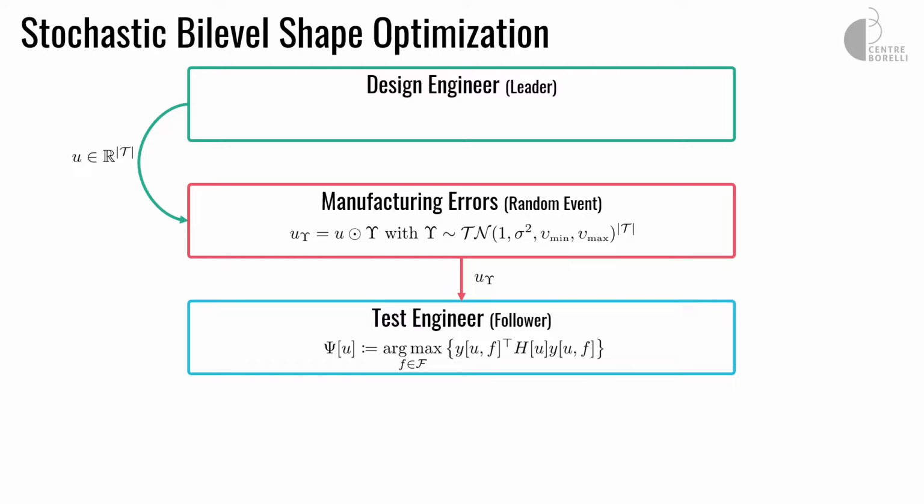And here we use something that's called compliance. It's basically the size of the displacement, but in the norm of using this H. If you think back to 4, it's actually the same thing, because there's just a mapping between J and U, so there's a relation between this. So this is the energy, the elastic energy under the forces. It's how much, it's called compliance.